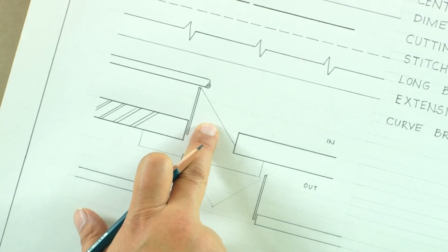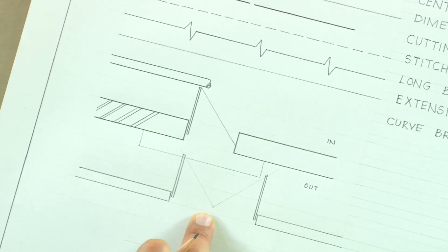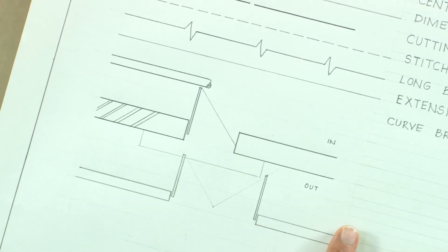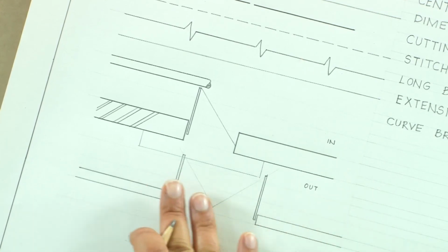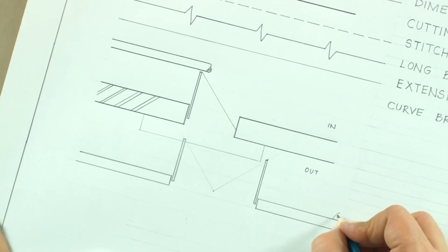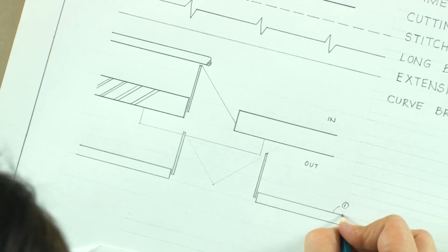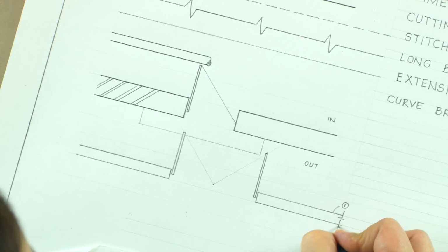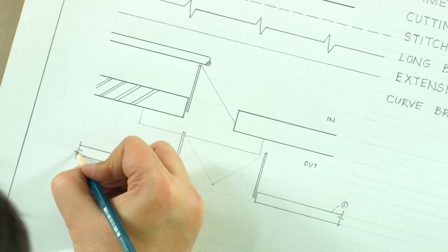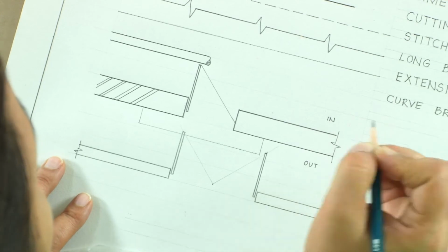So this is a single door only inside, single door outside. This is the representation for a double door which is opening like this. And when you are drawing this kind of a drawing, please mind the level of darkness. This line is going to be the darkest. So if I write in a descending order of darkness and thickness, this is the darkest because this is brick in section. And please remember that you will have to draw section lines on both ends of the brick. So you will draw section line on both the sides, whether it is here or wherever.